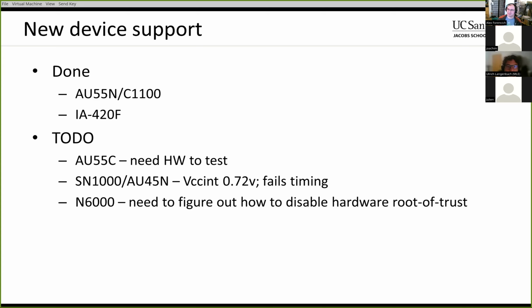The first problem I had to sort out with that one is the JTAG. I was thinking about laying out a board or something, but I had the connectors, and I'm like, yeah, I just want to get this done. So I air wired something with some of the fine blue wire and some epoxy to get a JTAG connector to stay put. If you're interested in what that looks like, I posted a picture of it on the Zulip, but it worked. I was able to talk to the card.